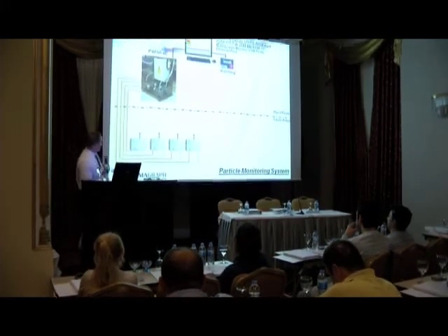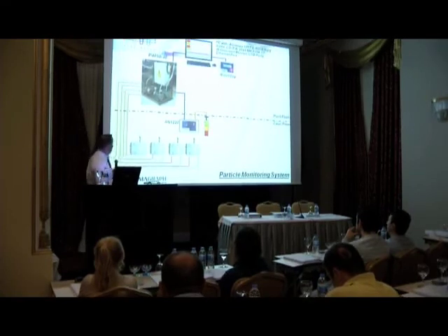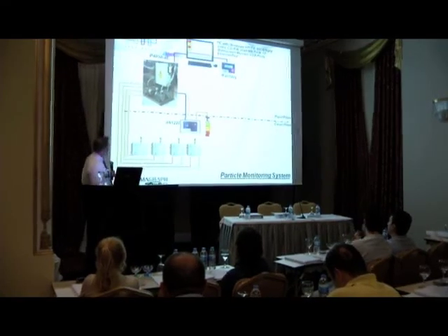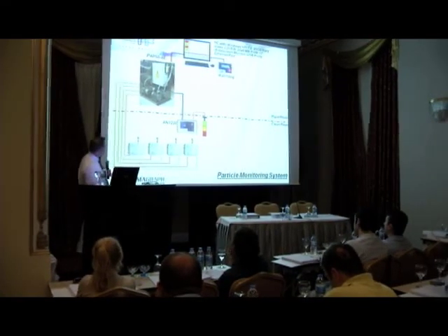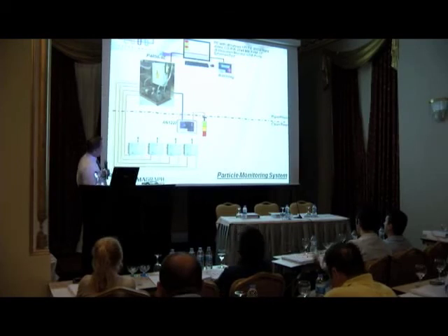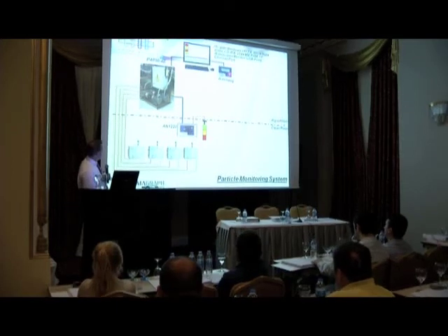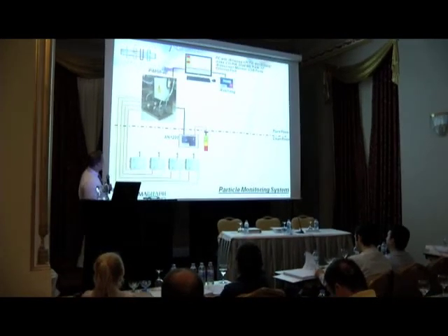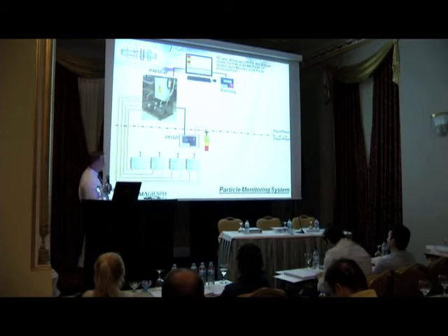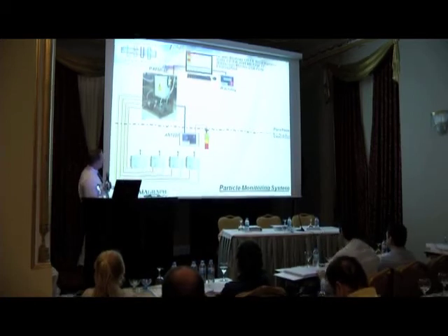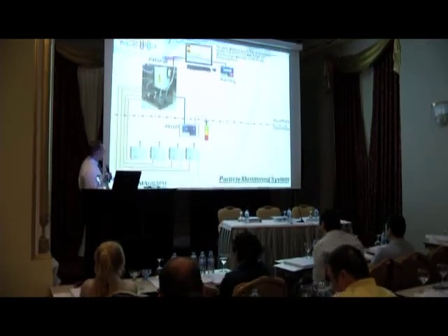Just some more diagrams really of what we've got on an FMS system. So we talked about, you've got a PC. There's another device we've now introduced which is called Watchdog. It's an optional item. What it does, it's constantly checking to see that the computer is operating and logging data. If this stops logging data, this will raise an alarm.